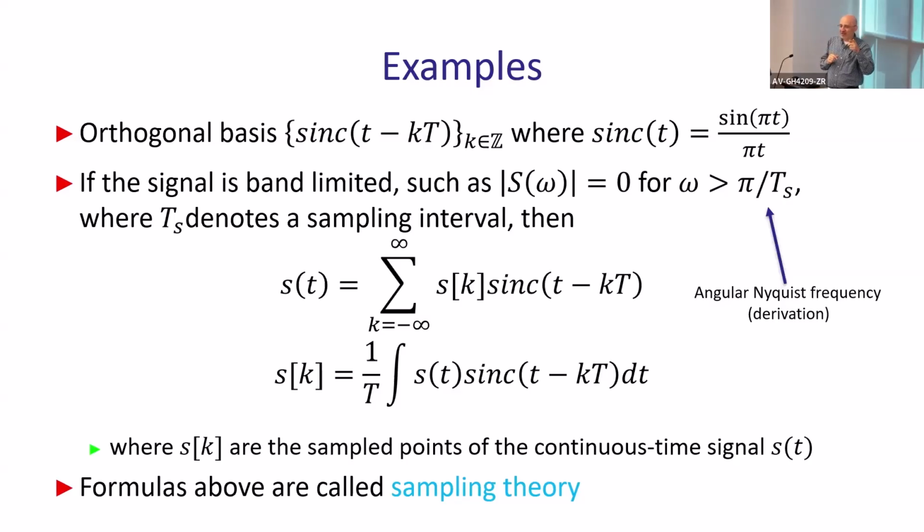So this theorem states that if you have a band limited signal, it can do only one possible thing between the sampling points. You have no other possibilities, only one, if you limit the band, the maximum frequency of your signal. That's it. And this is why before sampling, people always use a low pass filter.